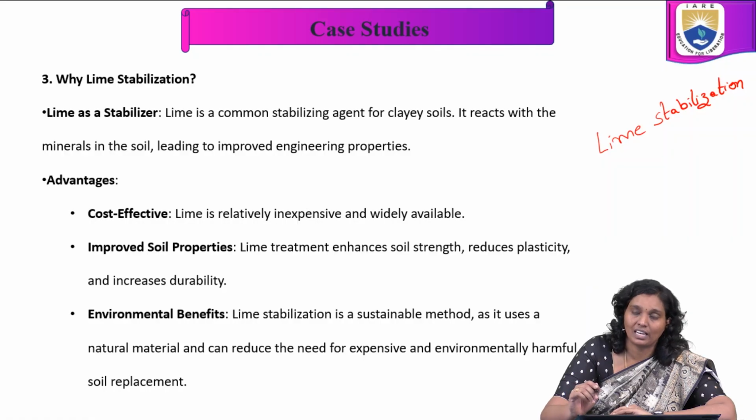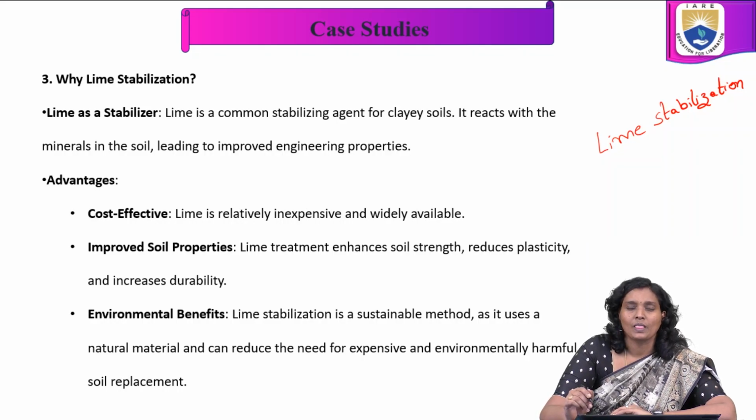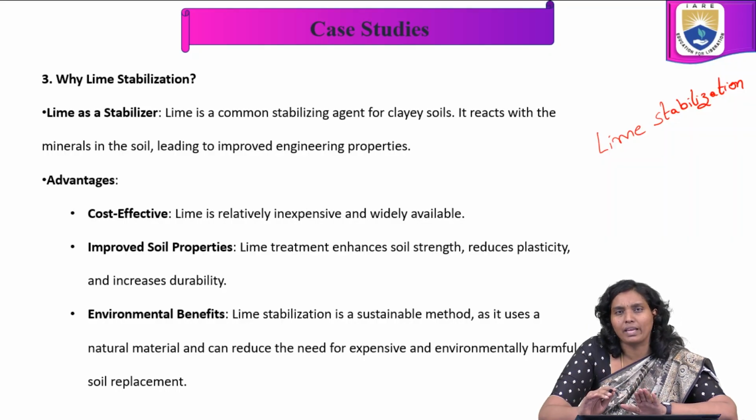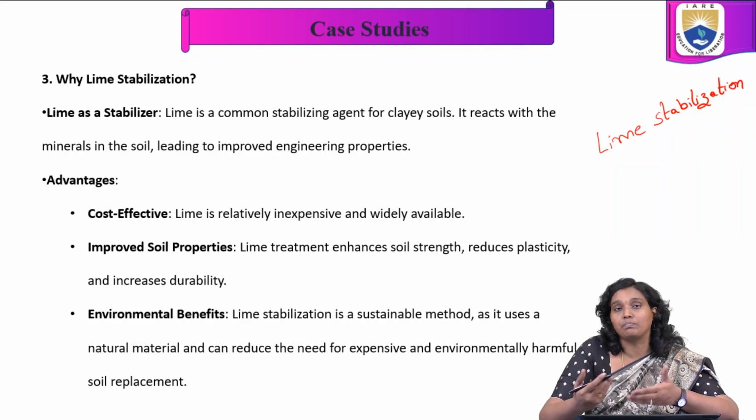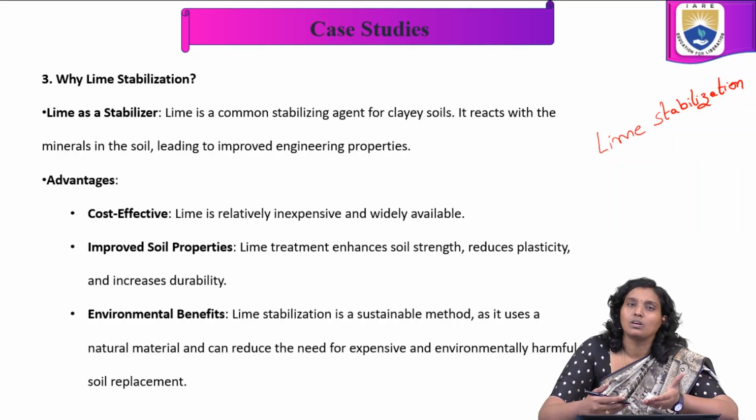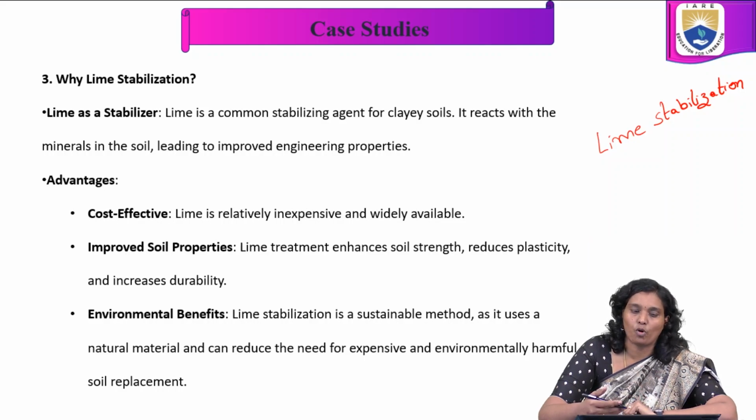Here lime is for clayey soils because it reacts with the minerals in the soil, leading to improved engineering properties: soil density, plasticity, and enhanced load bearing capacity. From that point of view, we have to understand these engineering properties.